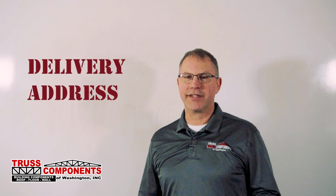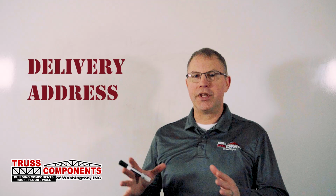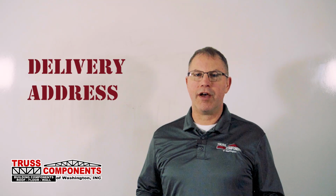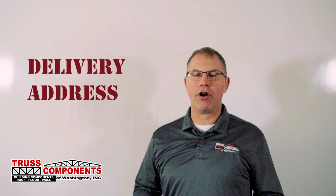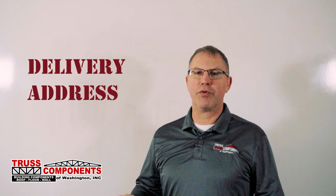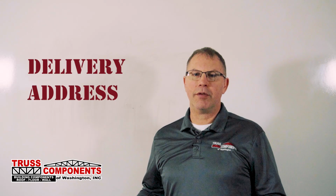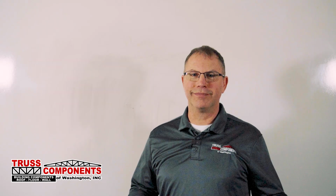The second of the 8 items that we need is a delivery address, and this serves a couple of purposes for us. One is we can pull up the delivery site on software like Google Maps and get an idea of if there will be power lines or trees or other obstacles to getting our truck into the job site and unloading the trusses. Also, it helps us to verify the snow loading that you've provided for us so that we can make sure that the trusses that we build are going to be the correct strength for the job site that they're going to.